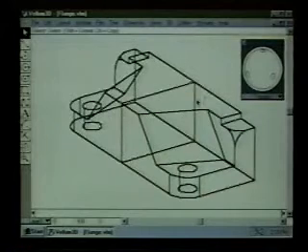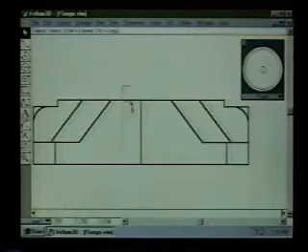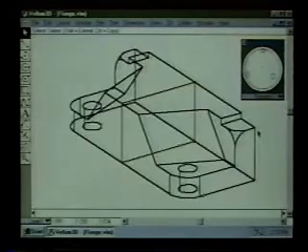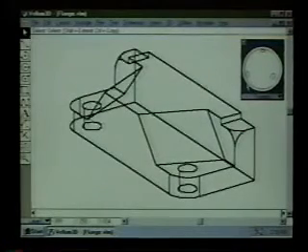Now it turns out too that I don't need this central rectangle anymore, so I need to select those lines and delete them. There's many ways to do that. Just to illustrate a concept, I will go to the front view, put a selection fence around this, and then when I go back to trimetric, I can see that those are selected. I can delete them with the backspace key, and they're gone.